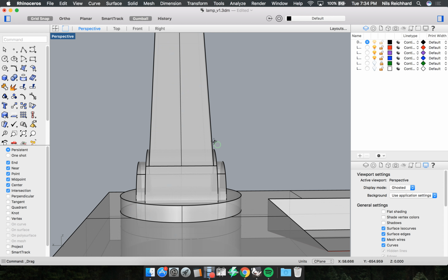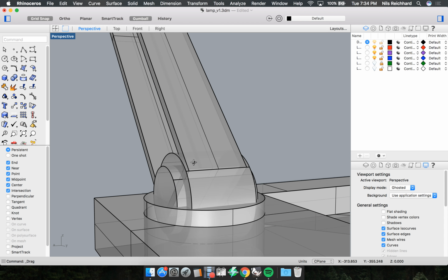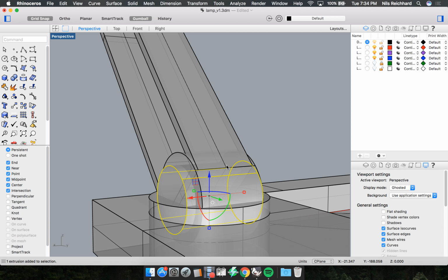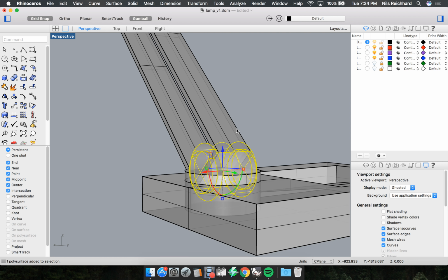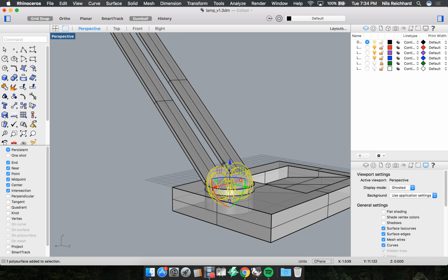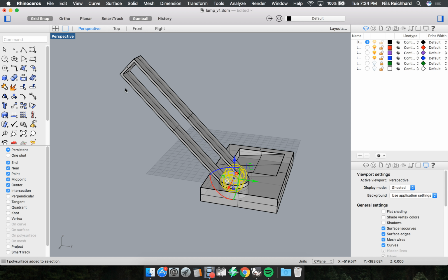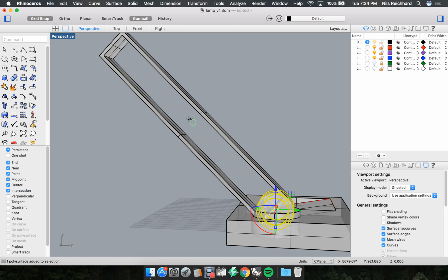I will give it a better look. So now I can actually take this cylinder and press Boolean Union here. This will merge both solids into one. So now you see I have only one solid. And I need this solid to also be in this other part of this object.